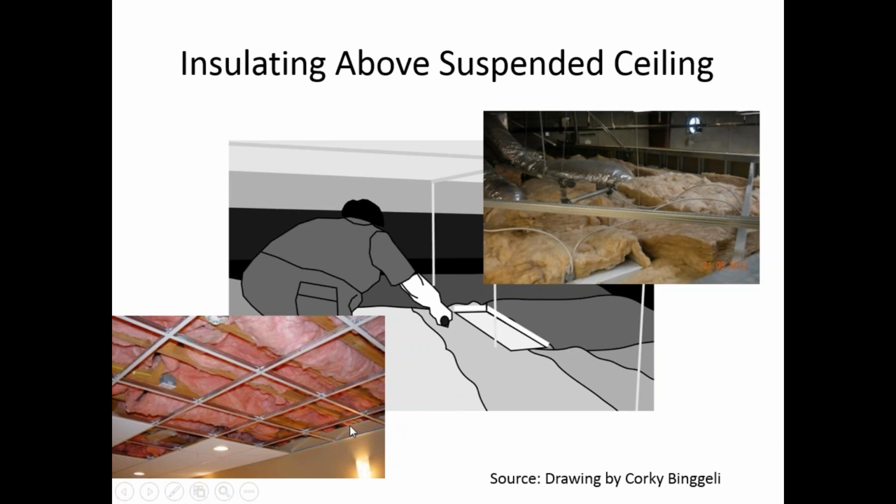This closes up that hole in the ceiling plenum just a little bit. Without it, you'll have a picture on 121 in your book where you have the less than full height partitions, and really walls leading up to that ceiling plenum without any type of insulation are going to have this direct connection almost with sound to the other side of that wall, because the partition doesn't go all the way up. So adding this will significantly reduce the sound.